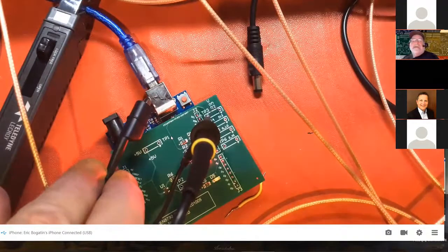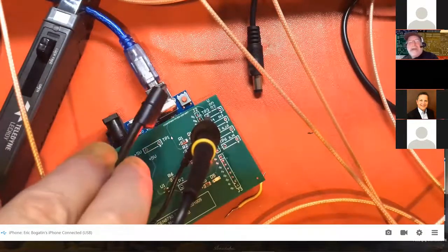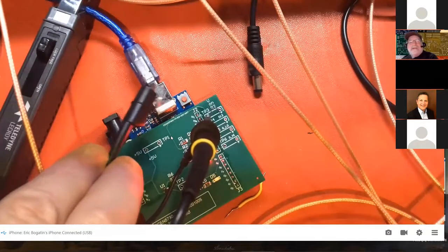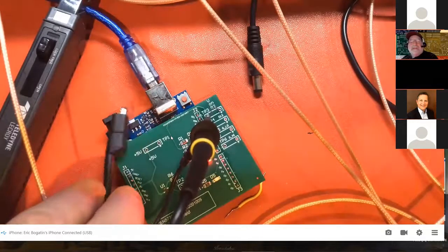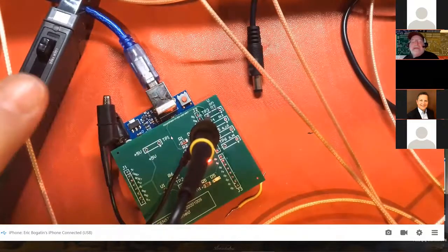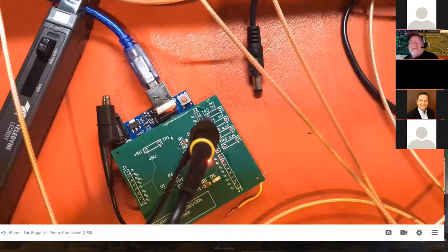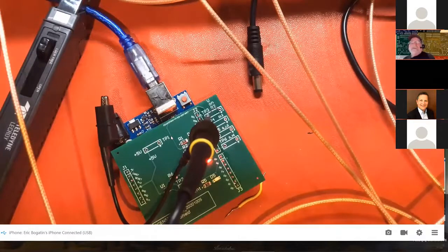But again, it's not just the bandwidth of the probe, the other problem is we are susceptible to RF pickup, and when we're measuring a high-speed signal with the 10x probe, we have basically made a radiating antenna, and so now we're polluting the near-field environment in which we're doing our measurement by using the 10x probe with the long floppy lead.